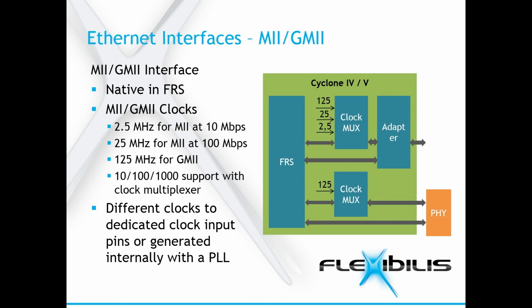When MII is used in the FPGA internally, for example with an interface adapter, typically a PLL is used to generate the different clock speeds. The clocks can be brought straight to the FPGA pins also. Note that the external input clocks need to be routed into the dedicated clock input pins. A trial FPGA compilation verifies the suitable pins.